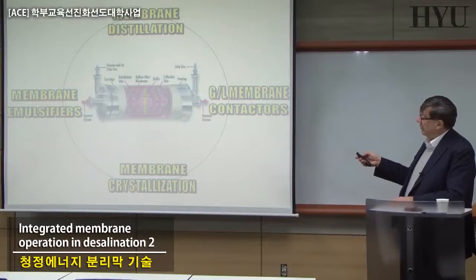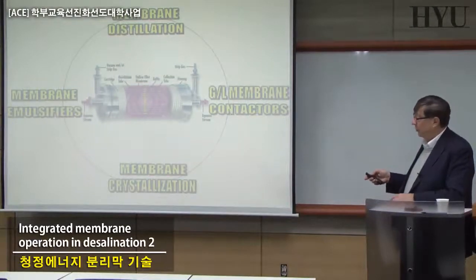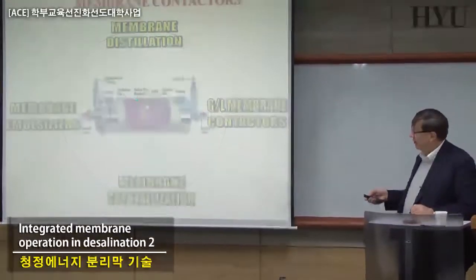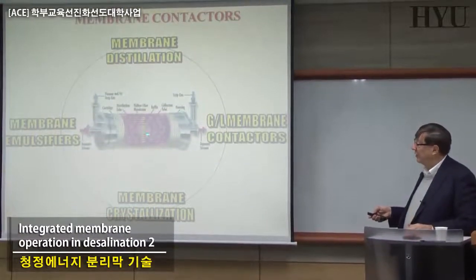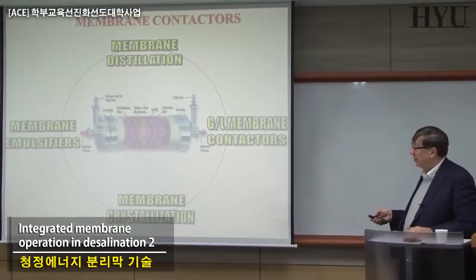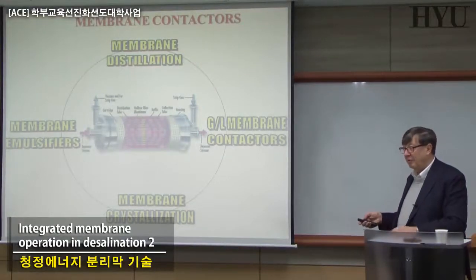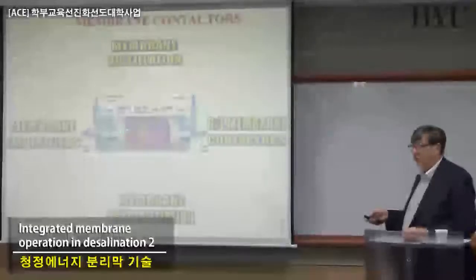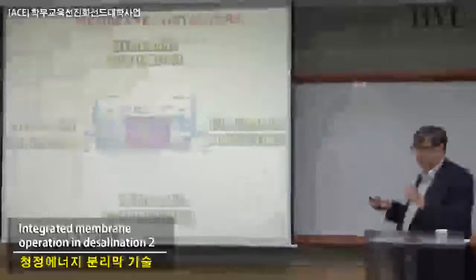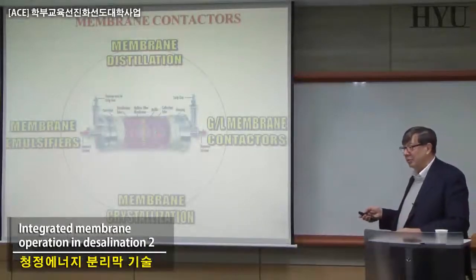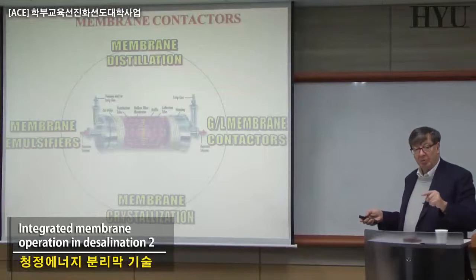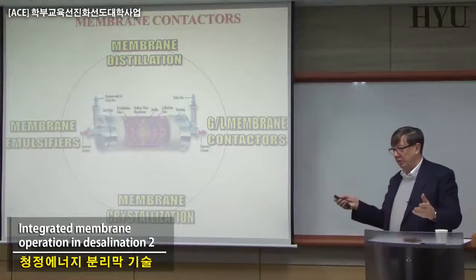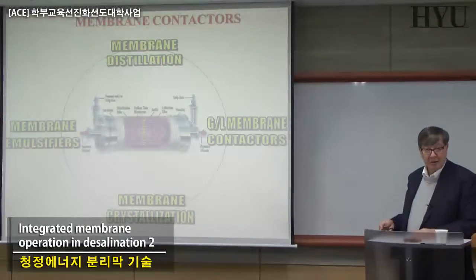What is membrane distillation? All these systems have another interesting aspect, consistent with process intensification: this module is, in principle, a typical membrane contactor. It's a module where you have hollow fibers of hydrophobic microporous membranes. This is an industrial one, called Liquicell, from one large company producing this. Mainly it was started for producing ultra pure water for the electronic industry, an application where it's very well utilized already.